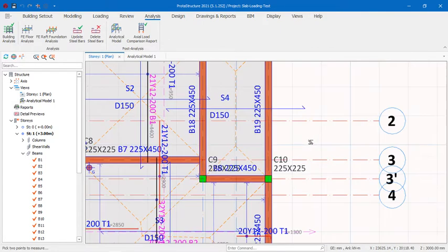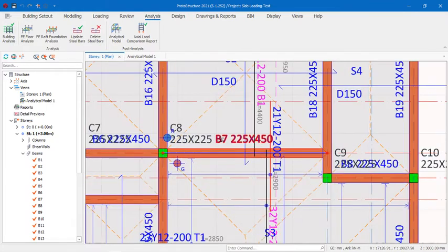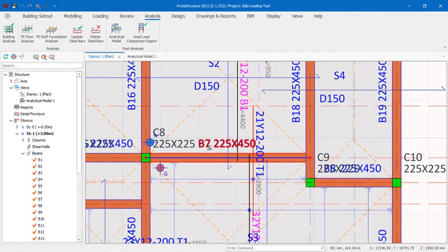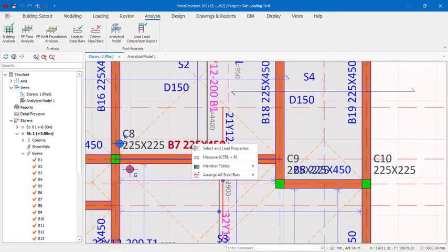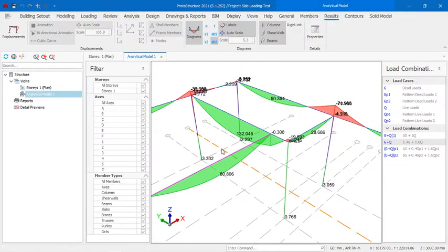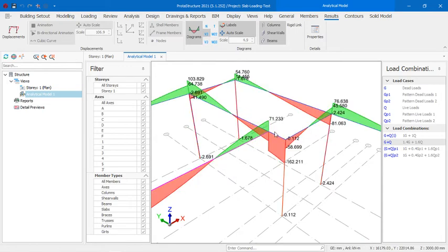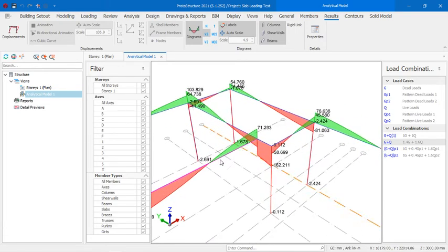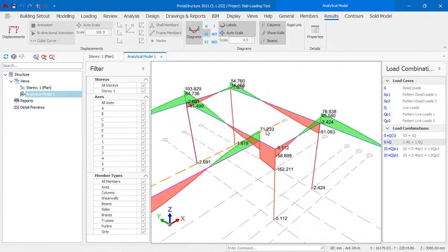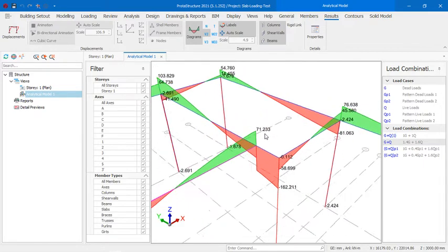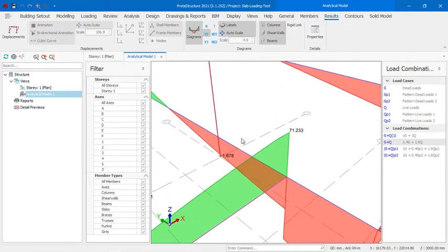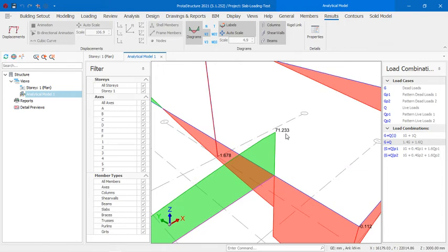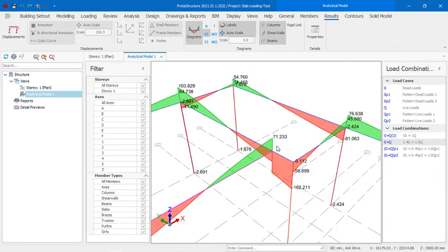Now when you have 650, like I said, there are two ways you can do it. It's either you add all the loads and calculate the shear force yourself, or you come to the analysis that you have run and check the reaction for that particular beam, and put it as point load for this beam. So in this case, let's say it's giving us 71 in this software.